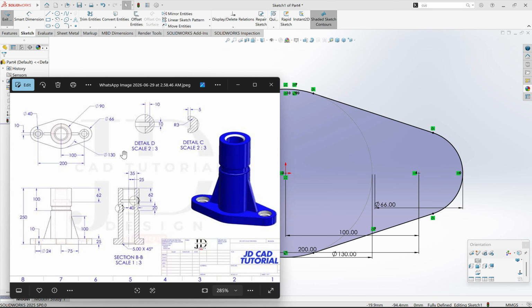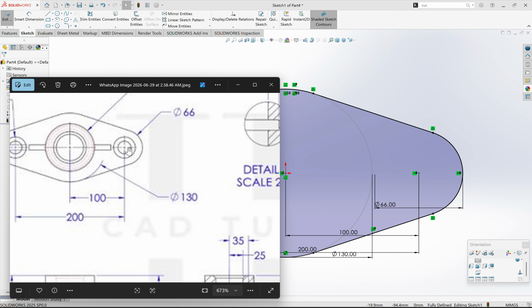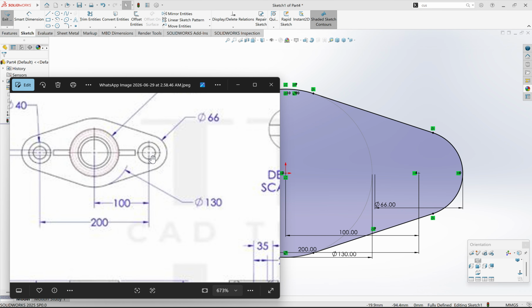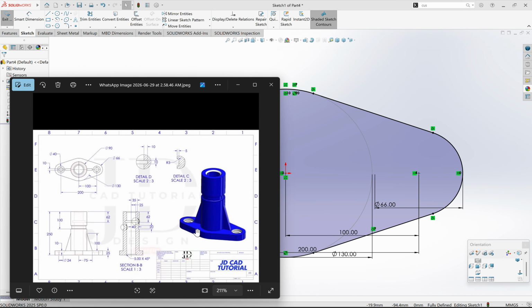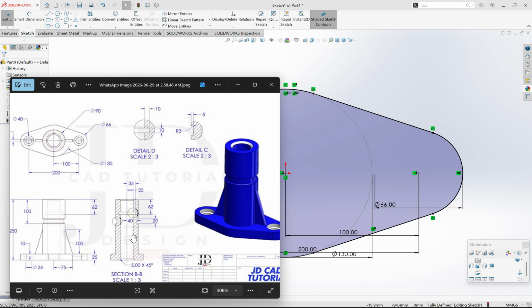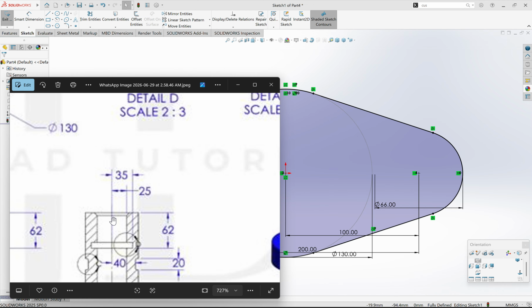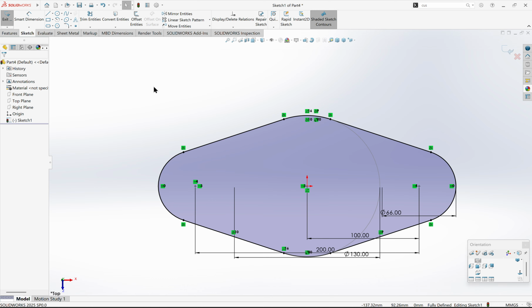Now, from the drawing over here, from the same center point of this outer circle, we're going to put another circle. In this one it has two circles, but we are going to do the first one. It's 24 in diameter. We're going to do this right now. And from here it's showing that it's a hollow place, so it has a radius of 25. If you look from the middle to the edge of here, it's 25, so it has a diameter of 50.